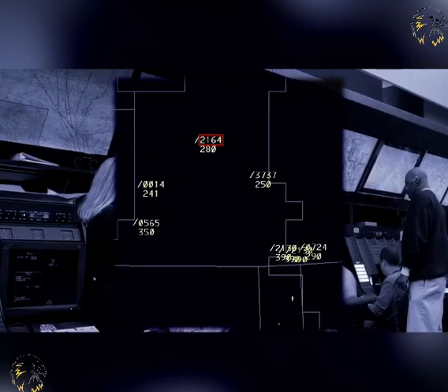You will remember that secondary surveillance radar equipment allows for the specific identification of aircraft by the employment of ground and aircraft-based equipment. Modern systems also provide for altitude information to be available, and the latest systems additionally assign unique identification codes to individual aircraft. This is called code conversion. Secondary surveillance radar use has its own standard procedures and phraseology.